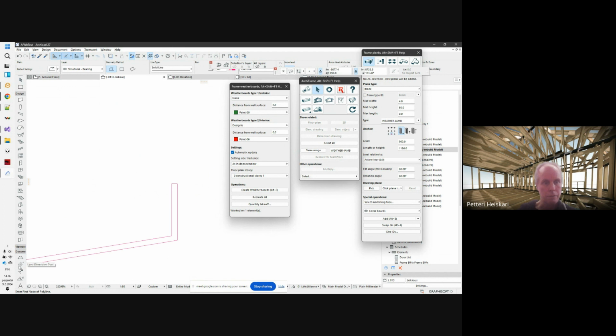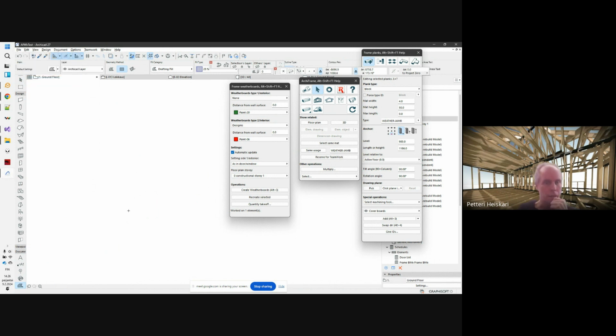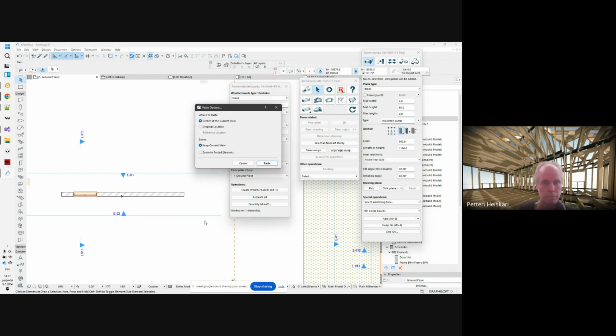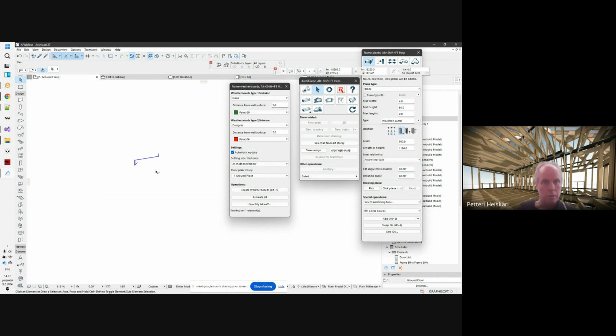And then, since ArchiFrame requires that the profile is a fill, I use again magic wand. So press space bar and then click inside the polyline. And then I'll copy this fill to the floor plan. I don't know, actually it might work in section also, but at least here it will work. And paste it here. So there we have it.